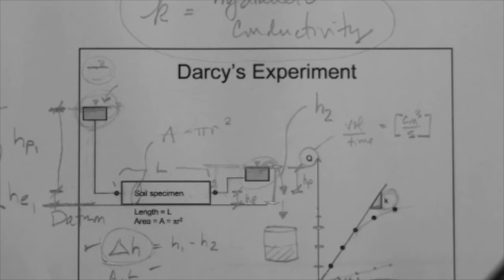This is not delta H alone, this is delta H over L times A. That parameter, that conglomeration of parameters here, is so high that there is a change in the flow regime. So the fluid starts flowing in the turbulent regime. So the flow becomes turbulent beyond this point.